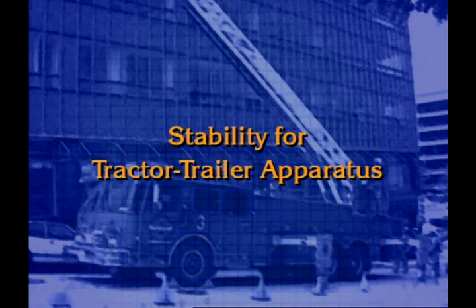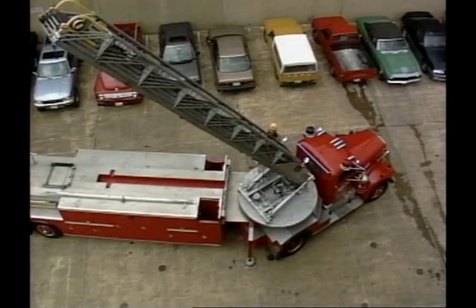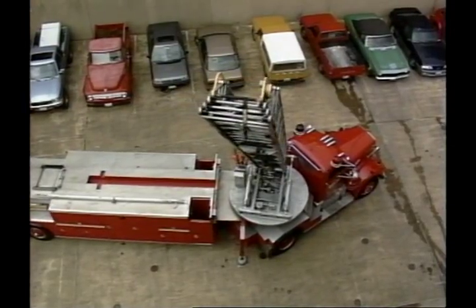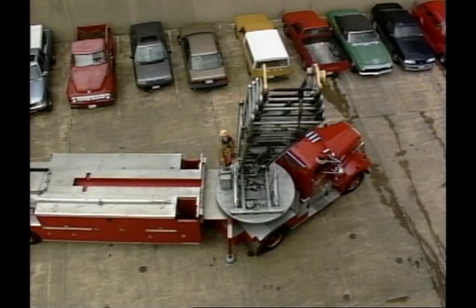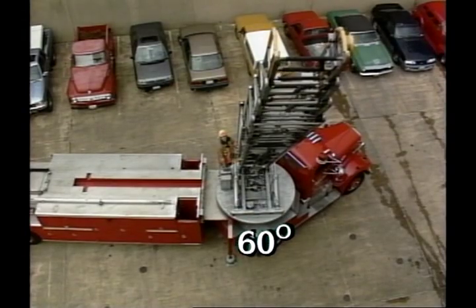To achieve maximum stability for tractor-trailer apparatus, you need to apply one additional principle of stabilization. Because stabilization is increased by widening the base of support, you can dramatically increase the stability base of a tractor-trailer vehicle by parking the apparatus at an angle. You can maintain maximum stability when you place the angle of the tractor at 60 degrees from the center line of the trailer.